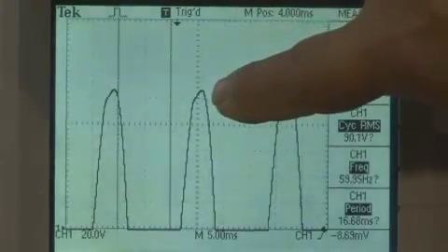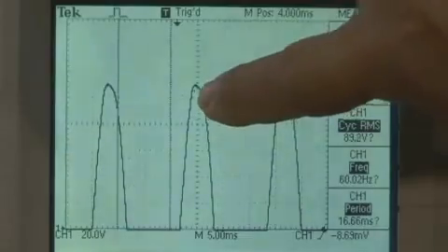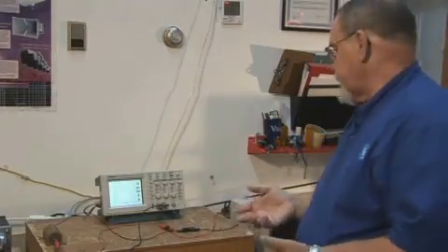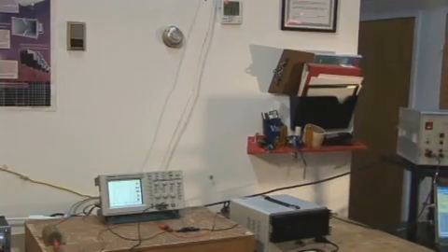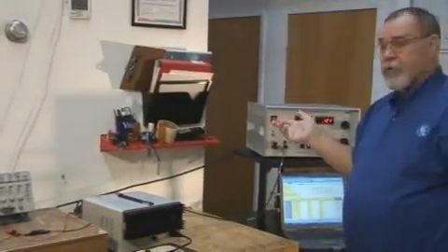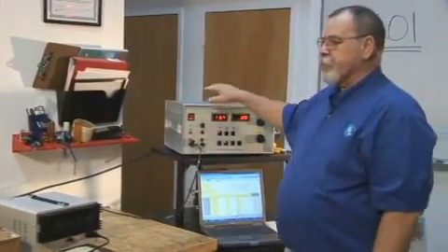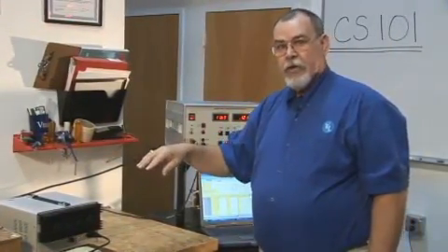And you see it's almost hitting this division and that division, which is 20 volts. So I have the peak-to-peak exceeding the 17.85, and I do not have my forward power limit met. I am below the 13.9 we had established. The test article is everything is operating correctly.